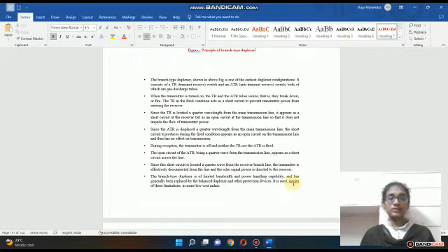The branch type duplexer is of limited bandwidth and power handling capability and has generally been replaced by the balanced duplexer and other protection devices. Because of these limitations, it is used in some low-cost radars.